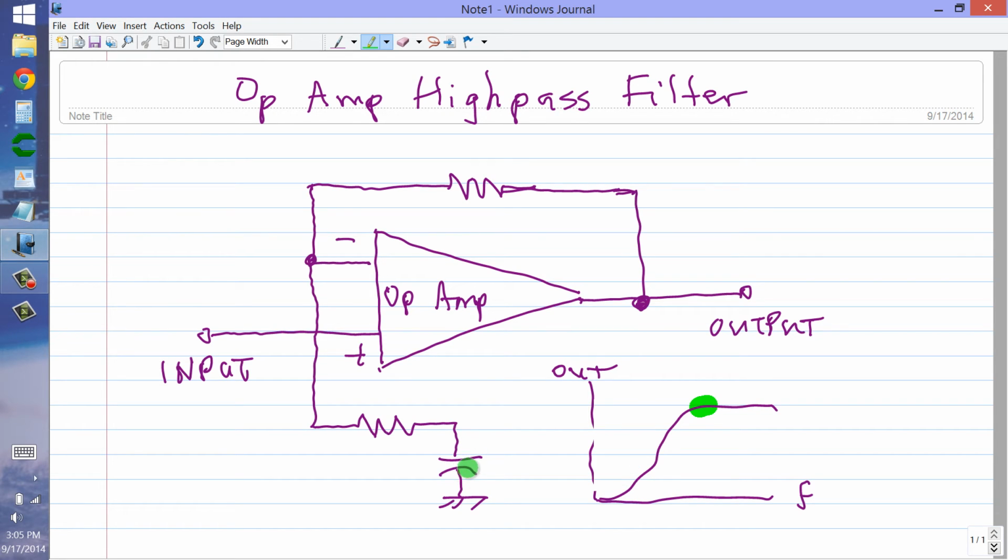That's because of this capacitor. Remember, its reactance increases as the frequency goes down. So as the frequency goes down, less and less of the negative feedback will get shorted out, so in effect you get more and more negative feedback. As the frequency goes up, the reactance of this device, the opposition that it offers to alternating current, goes down, so more and more of this negative feedback gets shorted to ground. That results in less net negative feedback and greater gain. Kind of convoluted, but the circuit is simple enough, wouldn't you say?